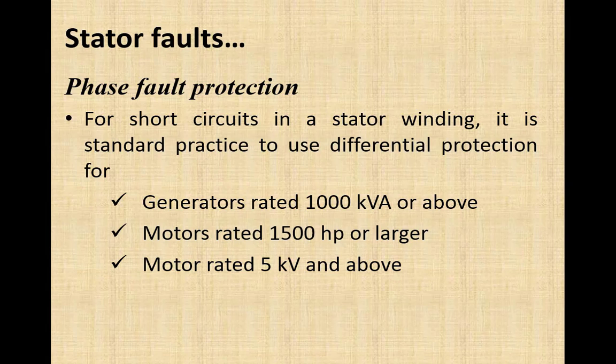Okay, if the generator size or motor size is less than these specified limits, then instantaneous overcurrent relay and time delay overcurrent relay can be used to detect the short circuit fault. If short circuit fault current is low, then we use time delay overcurrent relay, and if short circuit fault current will be high, instantaneous overcurrent relay would respond to those faults. But in case of large size generators and motors, it is standard practice to use differential relay for stator phase faults.